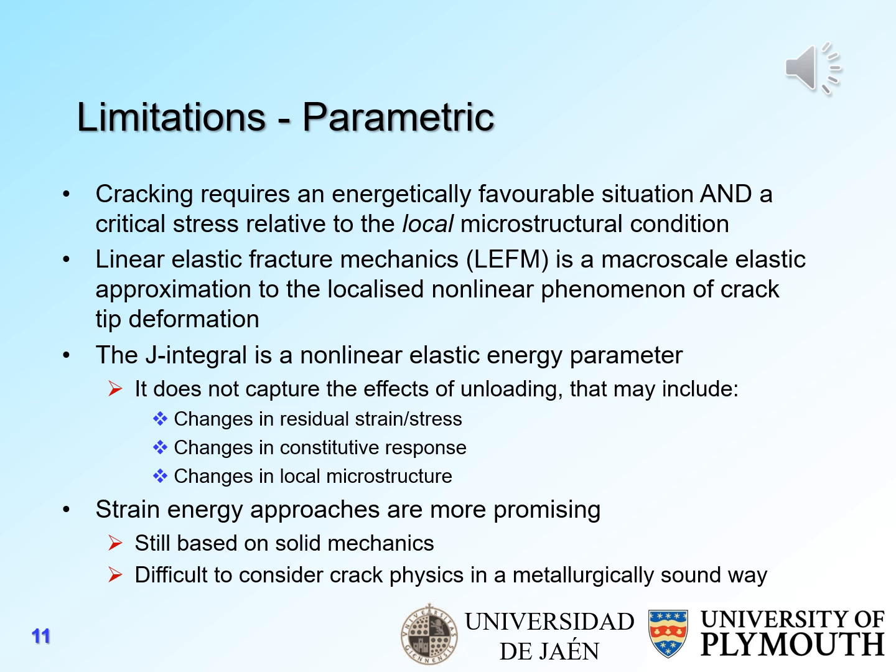The J integral is in its turn a nonlinear elastic energy parameter, but does not capture the effects of unloading. And these effects may include changes in residual stresses and strains, changes in the constitutive response of the material, and changes in local microstructure. Strain energy approaches are more promising, but they're still largely based on solid mechanics, and it's difficult to consider crack physics in a metallurgically sound way.